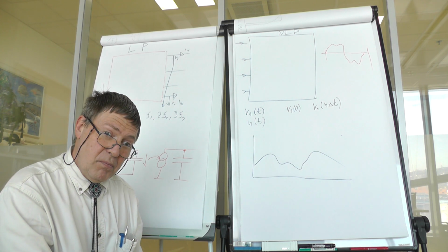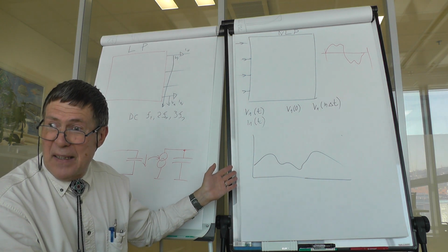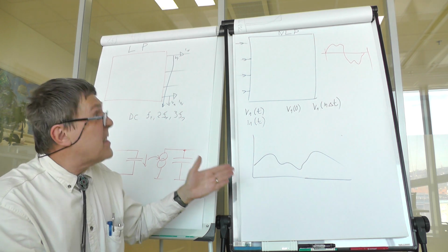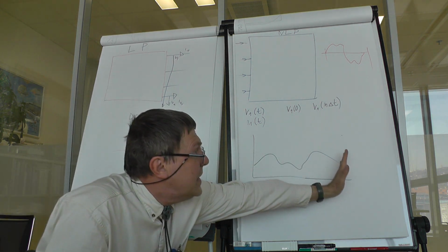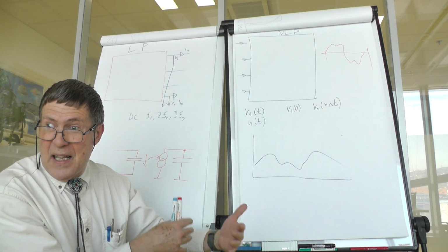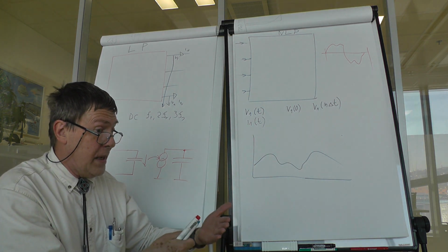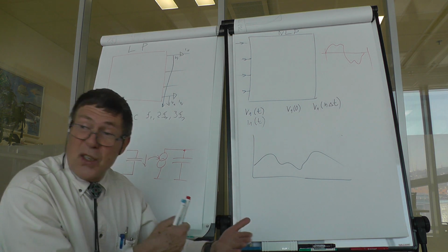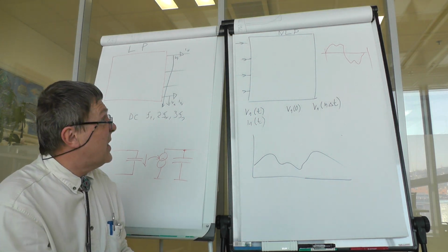And the simulator was working using harmonic balance, and this uncertainty in the correct frequency that would result from the oscillations has caused the numeric solver to be unstable. That is, we got no results, to be fair.